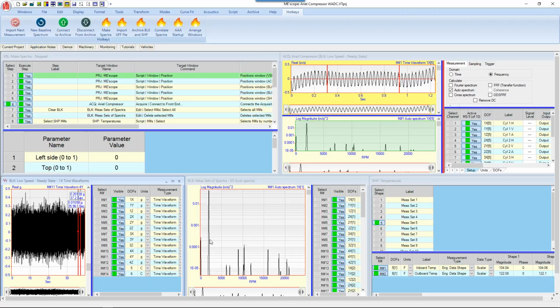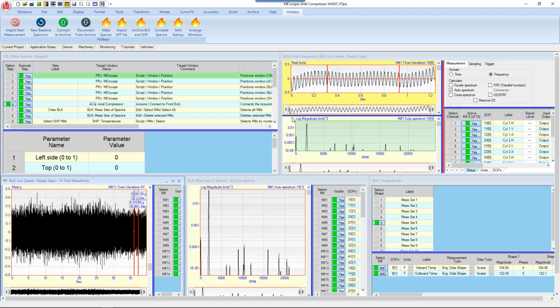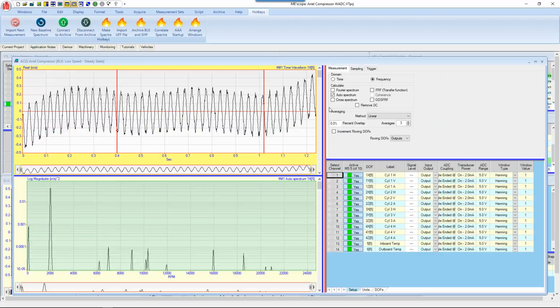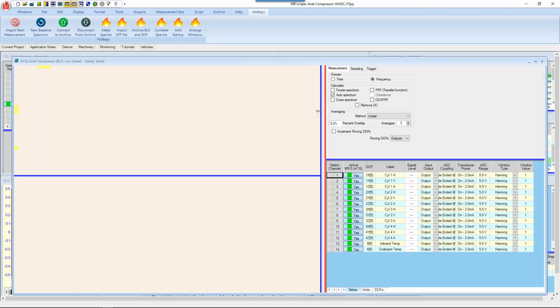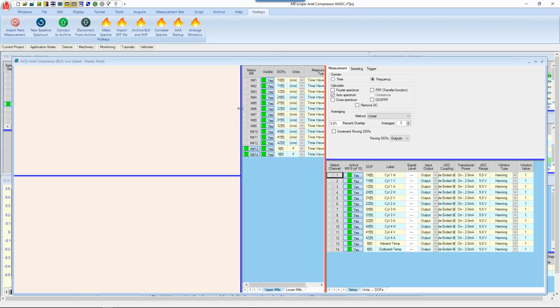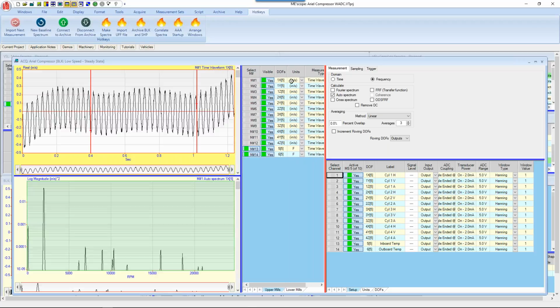And so the acquisition window is acquiring data out of this data block and post-processing. So let's take a look in here and see what it's doing. Quite a bit of stuff. Okay, so here's the 14. I'm looking at my upper traces. Here's some data coming in from the data block, and you can see that it's already integrated it to inches per second, and it's converted the centigrade to Fahrenheit.